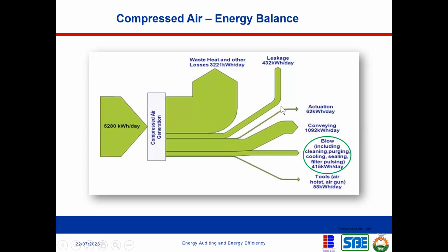So when you go to an industry to conduct an energy audit, you need to pay attention to air leakages, the compressed air leakage. If you notice air leakages anywhere, you have to recommend measures for them to stop it. Because the smallest amount of leakage can compound into a big amount of money in providing the energy to provide that compressed air. So it is very, very important to look at that.